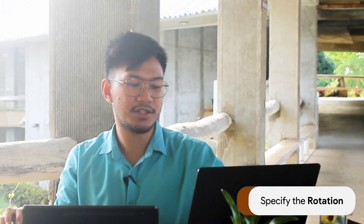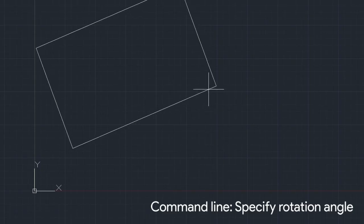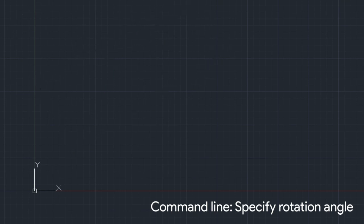Last one is your rotation. So how does your rotation work? So, let's try. First corner, and then now let's proceed to rotation. Type R, enter. And now, you are asked what the rotation is. Your rectangle is asking you for an angle. Let's just say the rotation angle is 30 degrees. So then now your rectangle is inclined 30 degrees from the x-axis.